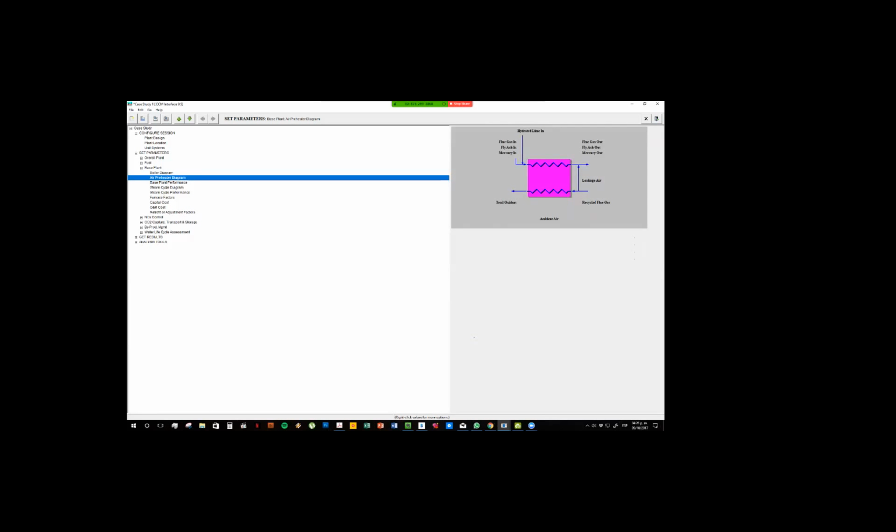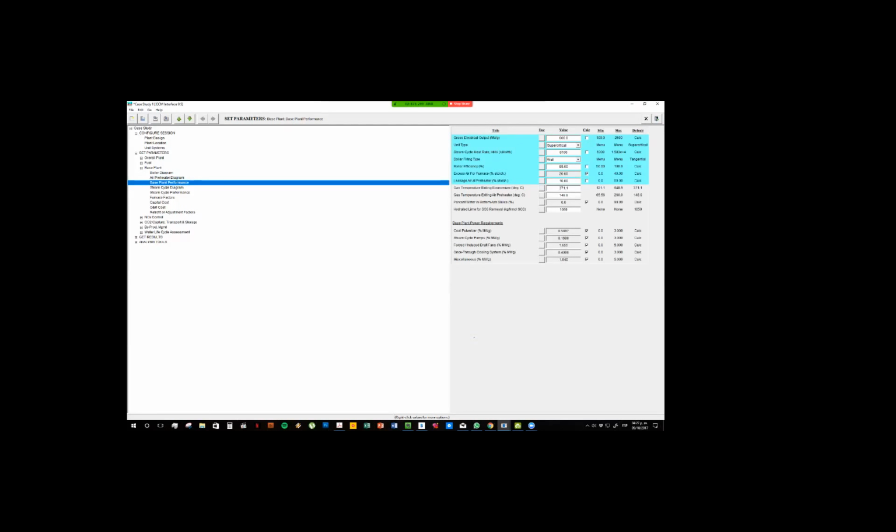That one is because you're recycling the flue gases, so you don't want all the gases to get into the boiler again. So you don't recycle everything. So you have a leakage air there, the percentage that you want to send outside of the boiler instead of recycling it, right?